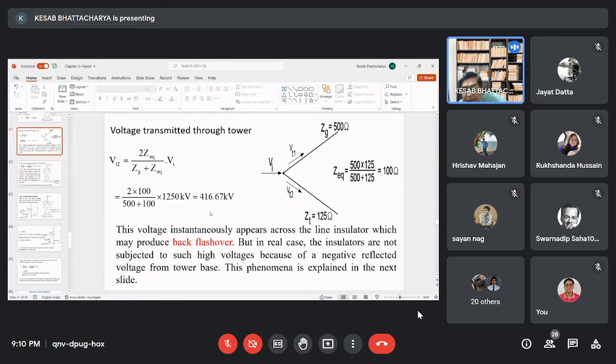Therefore, normally in the case of failure of suspension insulators, we have seen that it fails starting from the bottommost unit where it supports the live conductor. Then the flashover extends in the other direction, and finally across the entire string of suspension insulators the flashover occurs, and the live potential is transmitted from the line conductor to the earth at the tower cross arm.